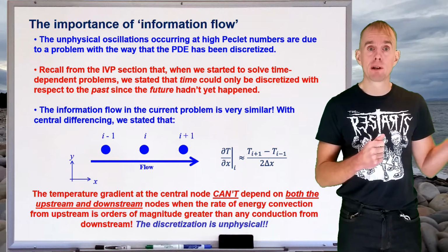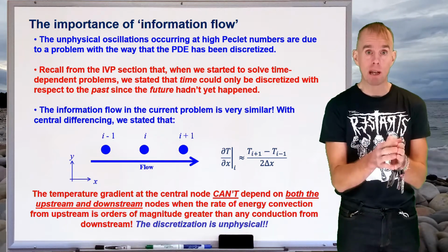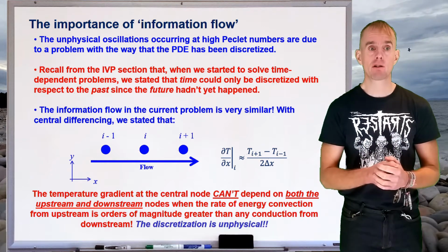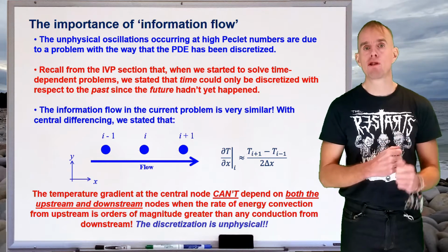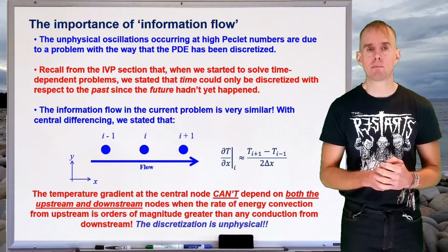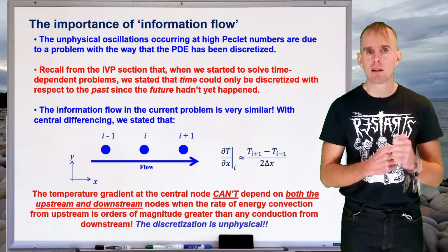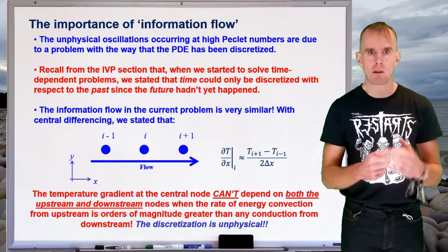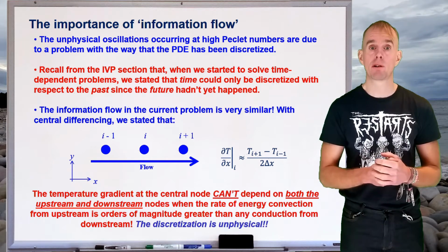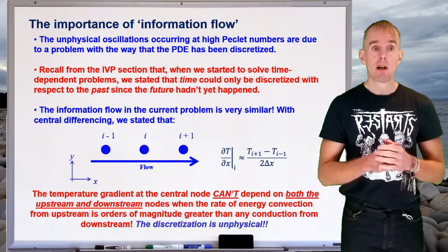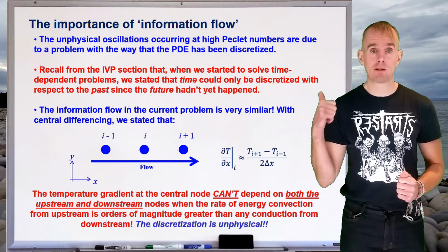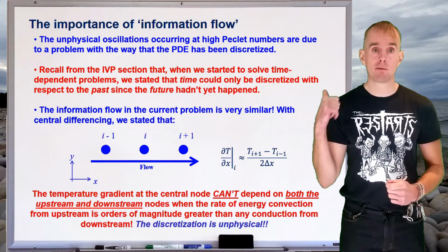If we imagine the fluid flow as a wind, if we face up into the wind, we will feel all the temperature coming towards me. So this is where the origin of the term upwind discretisation comes from, and this hopefully highlights the really important point of always keeping tabs on the physical situation for which you are solving the mathematics for. So we cannot use centred differencing to discretize the spatial domain for convection terms.